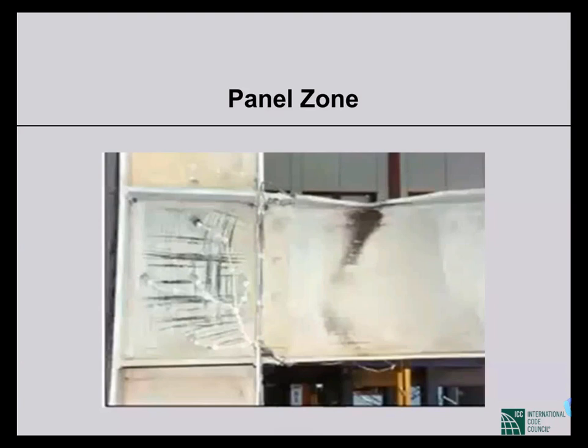While hinges form in the beam section, at that time there is a tendency of buckling in the panel zone, that is the beam column junction, the panel zone you can see between the stiffeners. So we have to design in such a way that this type of buckling is avoided. So we have to have some requirements for that, and the code provides those requirements for panel zones.